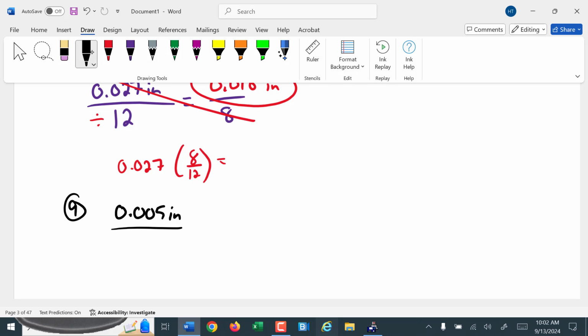So the acceptable is for a 10-inch flange. If we are using, as it says here, a 4-inch flange, we have to reduce that angular gap. Exactly. So I should get 0.002 inches.